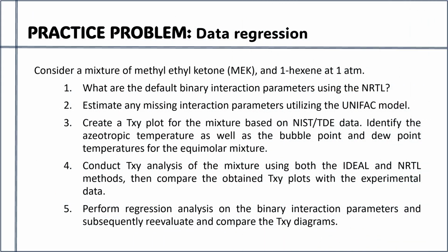Then create a TXY plot for the mixture based on NIST ThermoData Engine data. Identify the azeotropic temperatures as well as the bubble point and dew point temperatures for the equimolar mixture. Then conduct TXY analysis of the mixture using both the ideal method and NRTL method, and compare the obtained TXY plots with the experimental data. Also perform regression analysis on the binary interaction parameters and subsequently reevaluate and compare the TXY diagrams.